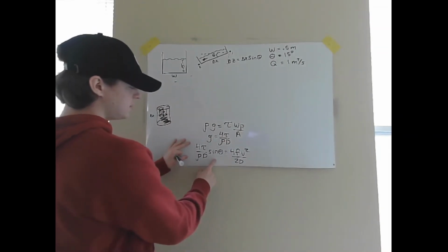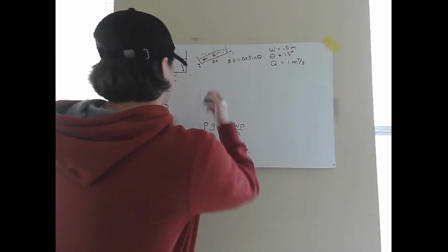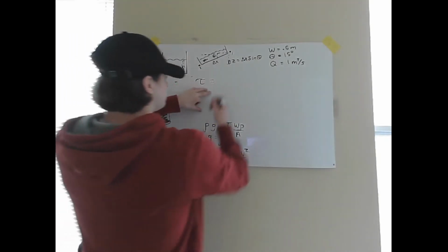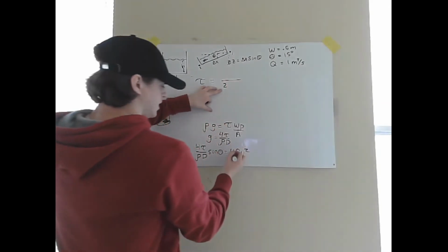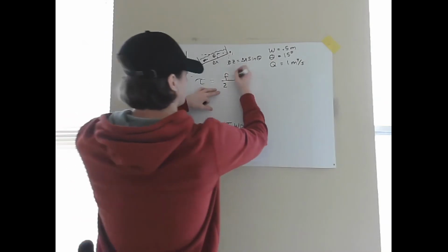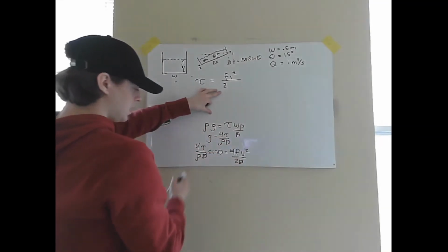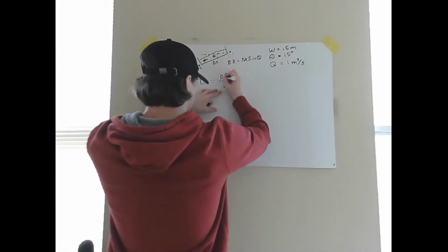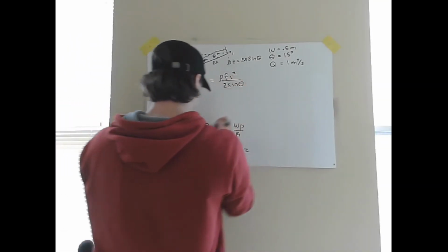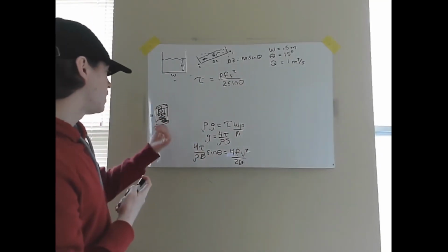And so to simplify this bottom equation, I'm just going to solve for tau. So start. Divide by 4. That's going to give us just a 2 in the denominator. These will cancel out. We'll have the Fanning friction factor. We'll have velocity squared. The diameters cancel out. And then multiply rho over to the other side. And then we divide by sine of theta. So this is the expression for the shear stress on a cylindrical pipe.